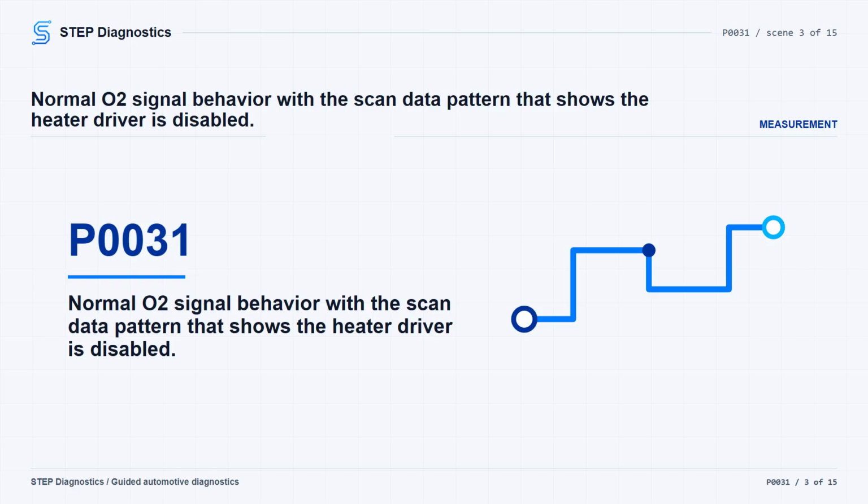If heater control is disabled, the affected O2 sensor bias signal voltage usually stays above 4.0 volts. A small amount of resistance, 3-4 ohms, may not set a heater control circuit code, but it can affect heater operation and set a sensor signal high fault. A heater circuit with 40-50 ohms resistance can increase the heater temperature reading on the scan tool for the affected sensor by as much as 700 degrees F compared to the other switching O2 sensors, and as little as 2.0 ohms can increase the temperature reading approximately 250 degrees F on the scan tool.